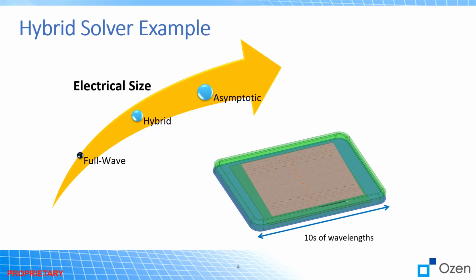The HFSS finite element solver includes advanced domain decomposition methods to efficiently represent the array using a repeating set of unique unit cells. Each unit cell can include different geometries to model the different parts of the array in the radome housing, and each one can be independently meshed, which significantly speeds up the solution.